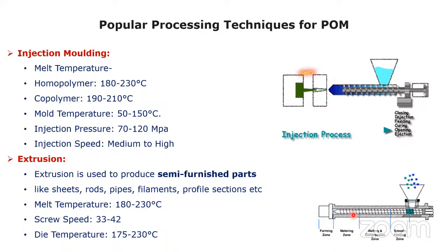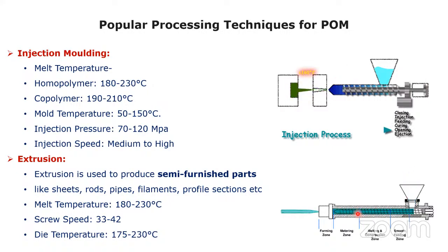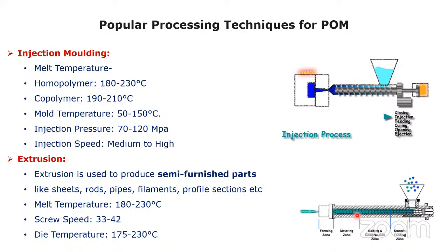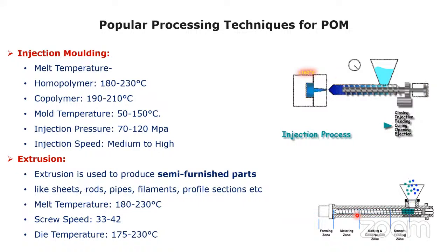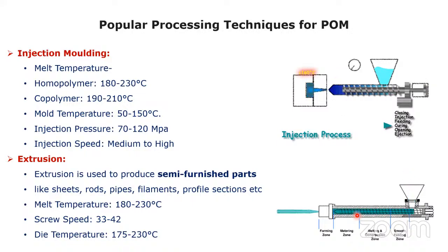In the metering zone, there are couplings that will move anti-clockwise, and some couplings that will move clockwise. It depends upon the type of extrusion. If it is a twin-screw extruder, it is co-rotating or counter-rotating, as you have mentioned just now. In the single screw also we fix the couplings so that one coupling will move anti-clockwise and one will move clockwise, so the mixture will be perfect.